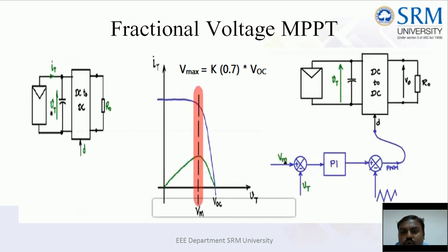Therefore, you can hard code this value in your coding. This approximation can be implemented in an algorithm, and you can see to it that your duty cycle is taken from your MPPT algorithm, which makes sure that your PV panel operates at a particular voltage VMP, which in turn makes the PV panel operate at the maximum power point.